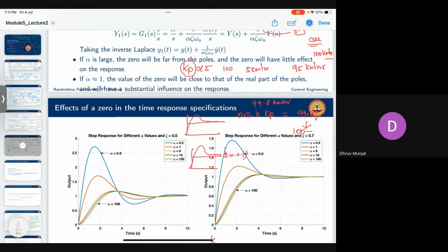That's what I'm saying. So this is proportional to the error, right? When the error increases, the proportion will also increase. When the error decreases, this gain will also decrease. So based on the change in the error, the control action will also change. So you cannot expect the control action to be stable all the time.